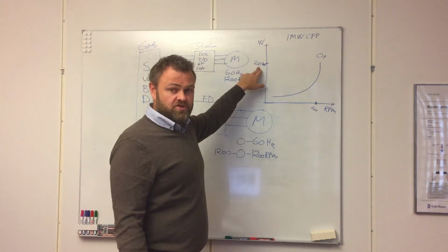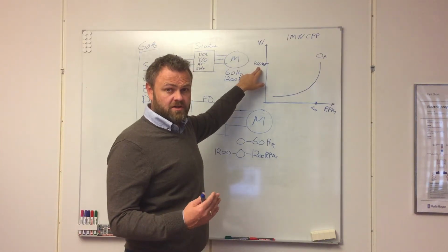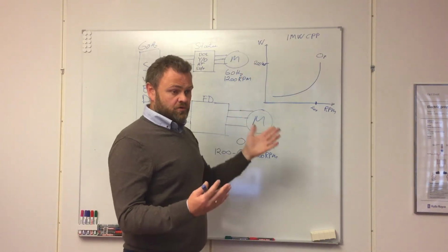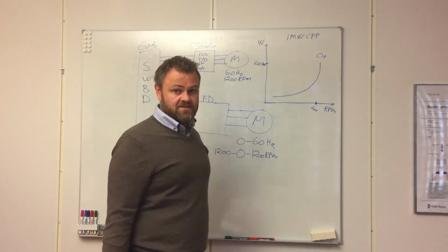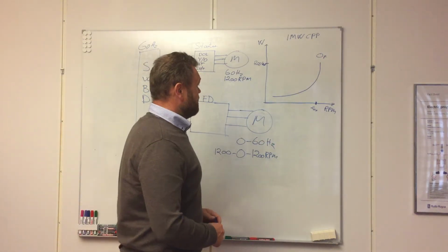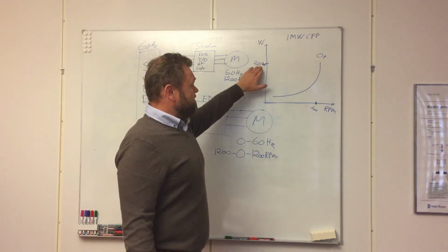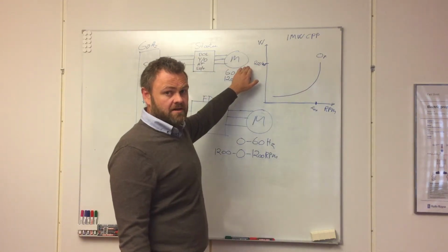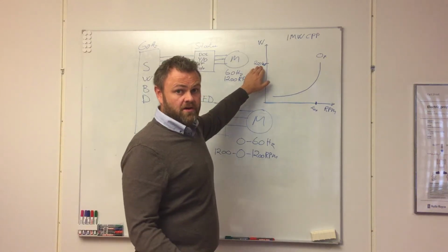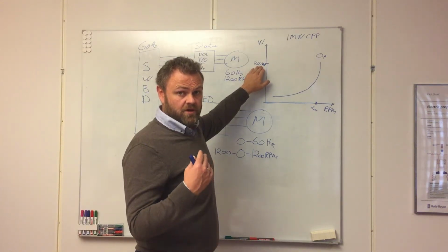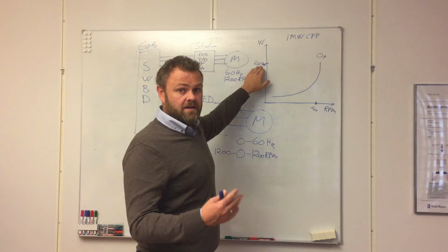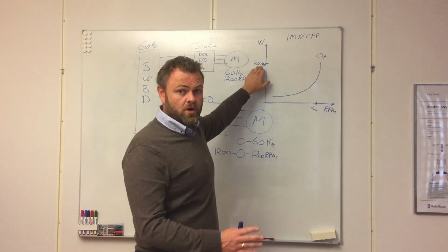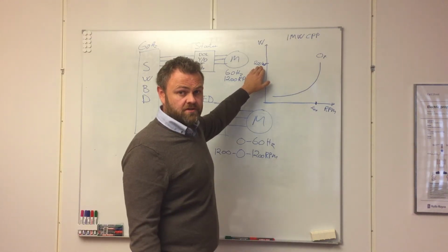How do you produce that megawatt hour? You have to produce it with your diesel engines. So obviously this loss for a fixed RPM propeller may be quite huge if you're spending a lot of time in low load conditions.